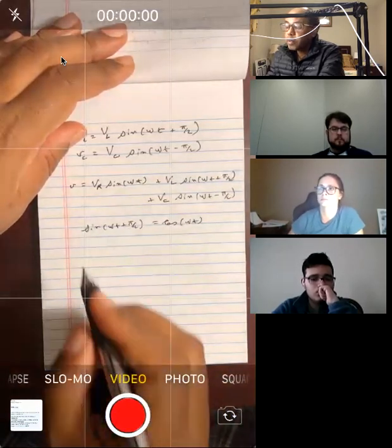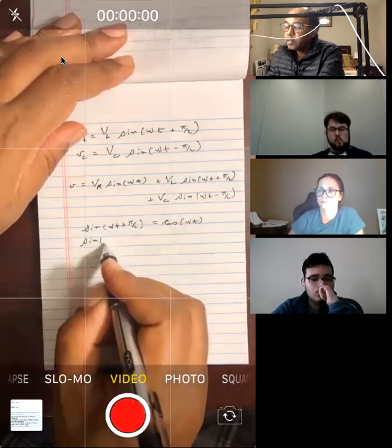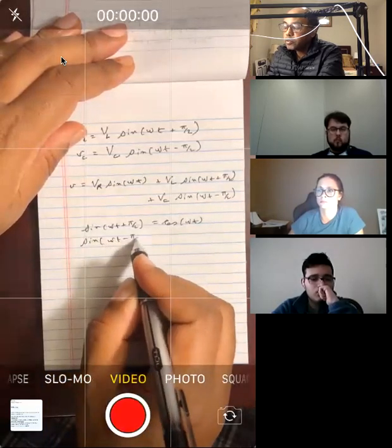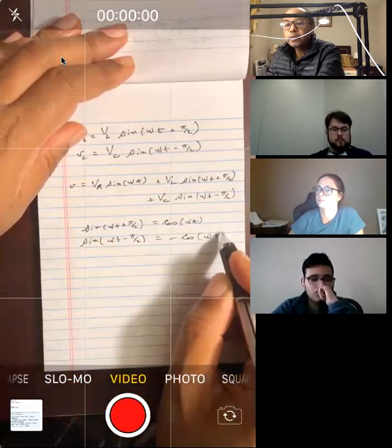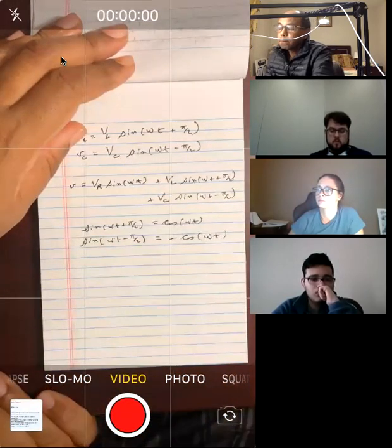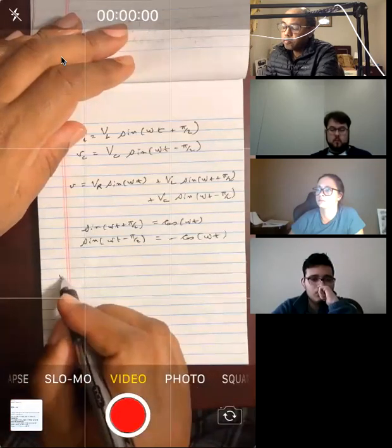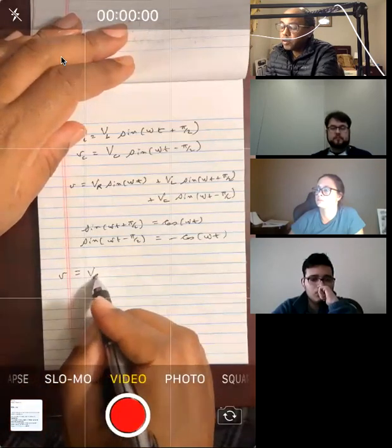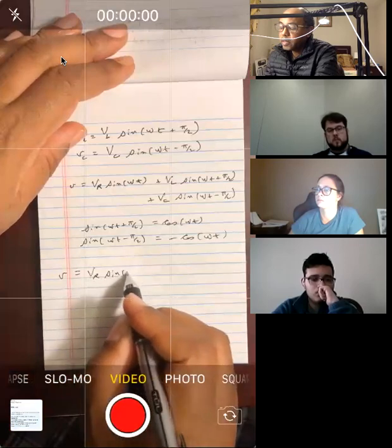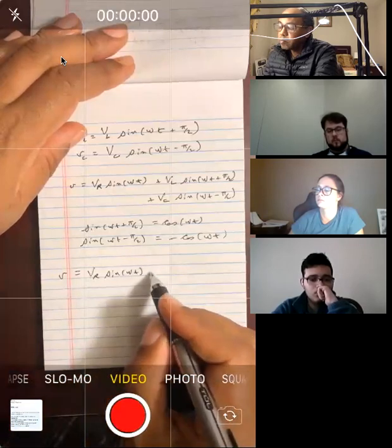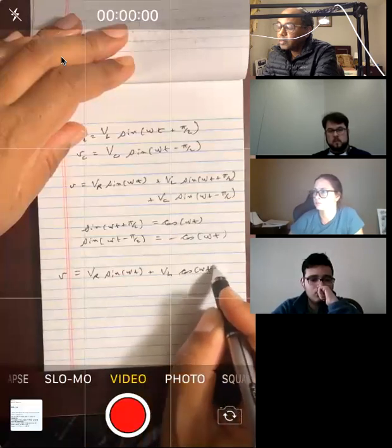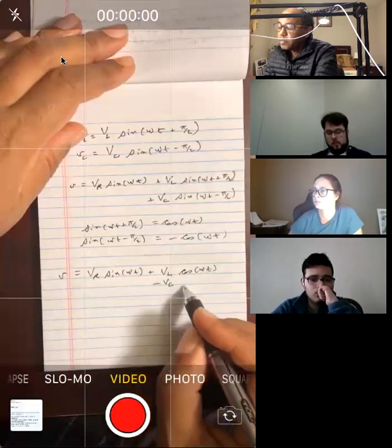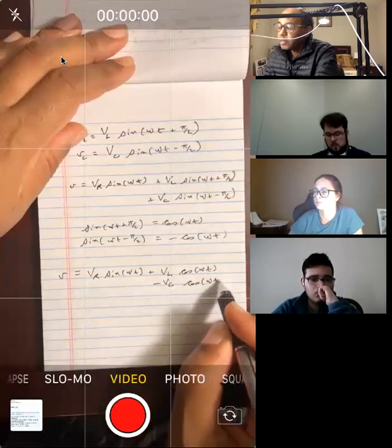Okay, if you expand this one, sine of omega t minus pi over 2, you'll get negative cosine of omega t. Okay, all right, so we have the following: V equals VR sine omega t plus VL cosine of omega t minus VC cosine omega t.